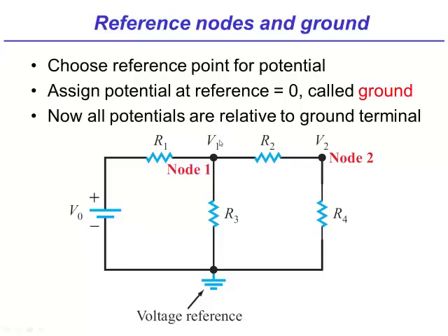So when I say what is V1 and my friend says V1 is 4 volts, what I mean exactly is that the voltage difference between this point here and this point there is 4 volts. Likewise, if my friend says, oh, I solved the problem and V2 is 9.5 volts, what they mean is that the voltage difference between node 2 and my reference node is 9.5 volts. It's always relative. The differences never go away. It's just that they become implicit in the way we describe the circuit.